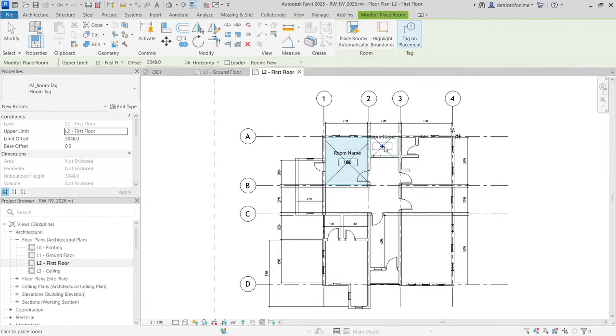This is a veranda, by the way. It's also going to have a room because it is surrounded by the railing. I think the Revit actually considered that to be a room as well. But for now, I'm not going to click that. Let's go ahead and click this room. And there's another room inside of here, which is the bathroom. It's really small. And there's a study over here. And this is the stair room. But the stair room and this other space here is quite different. So you have to use a room separator to do that.